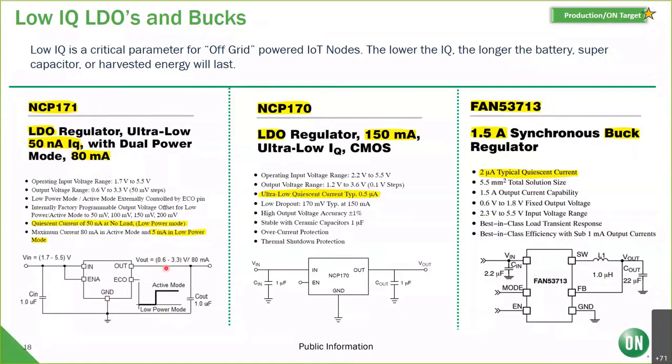When you've got an IoT edge node that's battery powered, it's sleeping, let's say, 99.9% of the time. A lot of MCUs now and SoCs and ASICs, one of their big claims to fame is multiple levels of sleep mode. And certain things are powered up and running during different levels of sleep mode. The whole point is that sleep load is typically less than a couple of milliamps. So this is a great device to use for a battery-powered IoT edge node because when your MCU is asleep, this is hardly burning any power at all. I mean, 50 nanoamps is barely measurable.